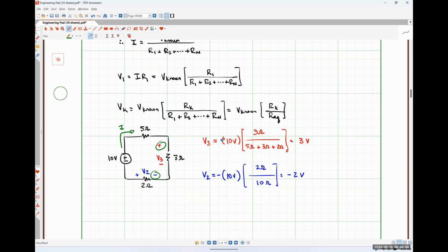Yes. Question about the voltage leaving currently 10 volts. Mm-hmm. Because it leaves on the positive side, why wouldn't it be a negative current? So we are making an assumption here, and it is an extraordinarily correct assumption because there's literally no other way that this circuit could work, that the 10-volt source is supplying power to those resistors, because all the resistors can ever do is absorb power, right? So the current leaving the positive polarity terminal is literally just telling us the voltage source is supplying power in the system, under the assumption that the current's flowing that way.